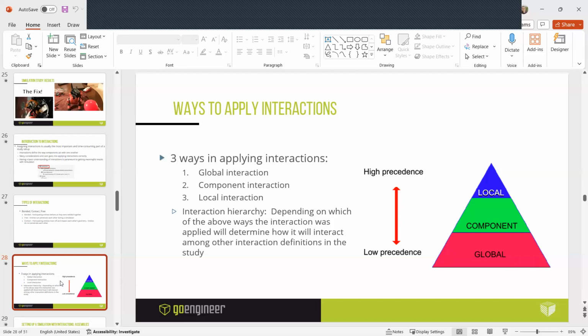Now, why don't we always just do that? Well, because in SolidWorks Simulation, the software has to organize and set up a contact event or an interaction event. So it needs to figure out scenarios for all possible combinations of faces and edges and points. That's going to give you a huge calculation that you're going to have to run. And that's why, if you have a lot of component interactions, it takes a long time to set that up and run through that phase of solving the study. You may have seen that if you run simulation.